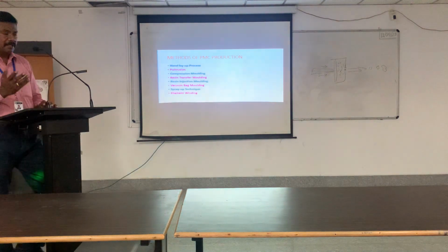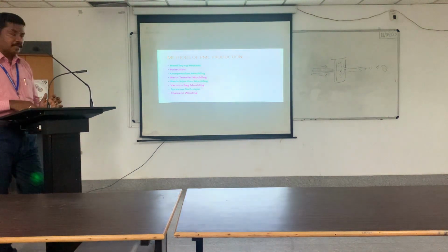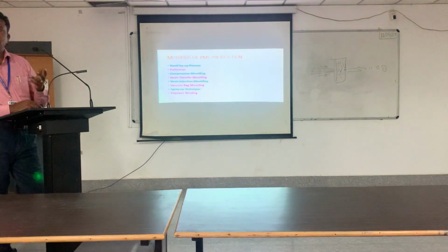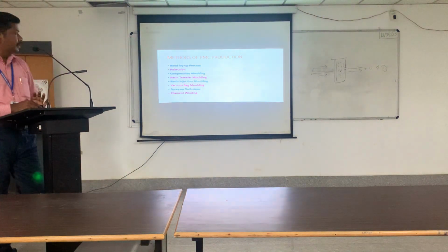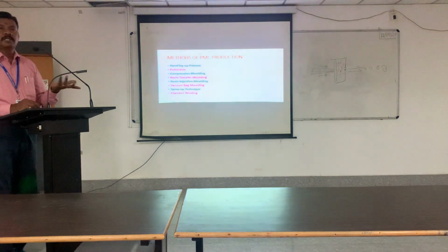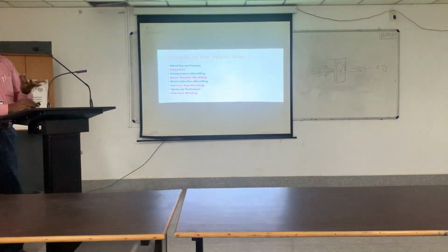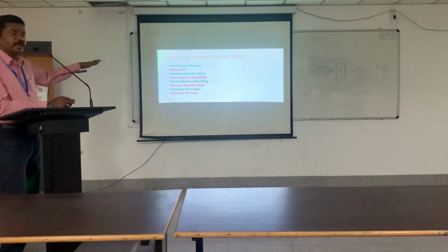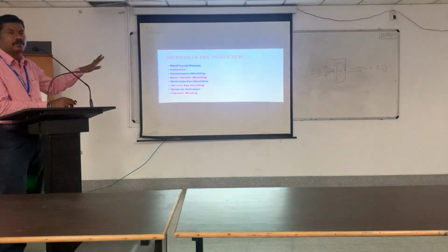Hand layer is the open mold. Very good. Vacuum bag molding will have two parts, closed as well as open. Spray up technique is the open. Okay, filament winding is also open. So mostly compression molding and resin transfer molding will be closed categories.